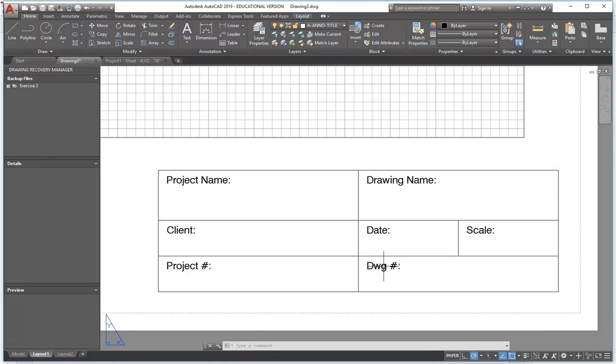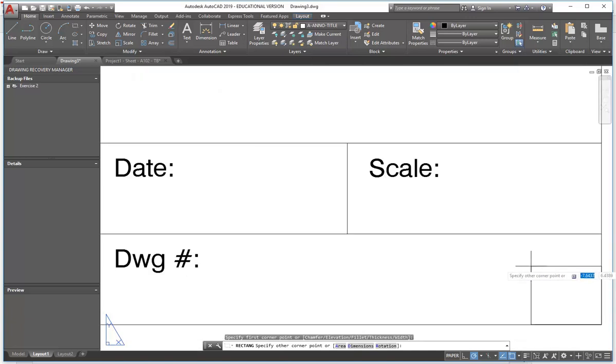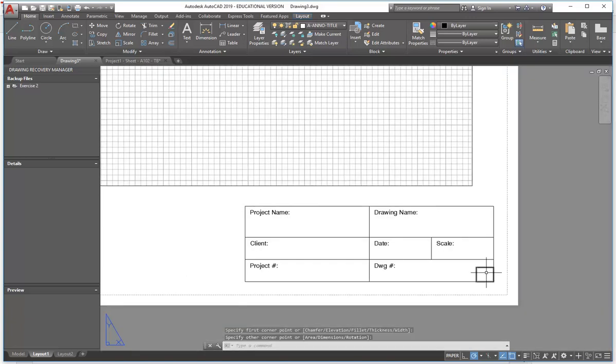Yeah, so I've got drawing number. That'll do. But yeah, you're on the right track. So yeah, the version or the amendment should go, or can go, with the drawing number. So often you'll have a little extra field for that. And so I'll just draw in maybe just a rectangle even, for my little letter for the amendment number. So it'll have an A, B, or... Yeah, oh yeah, for this you will, because you need to do amendments.